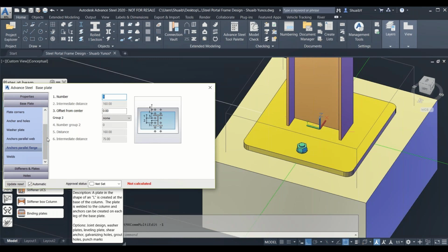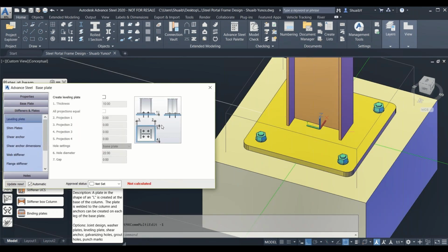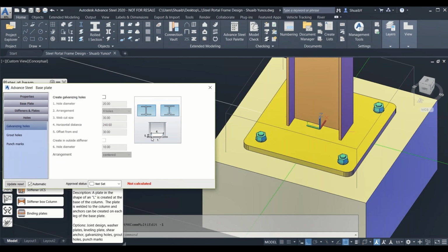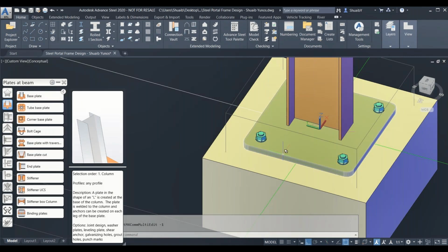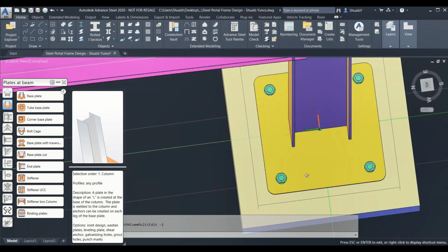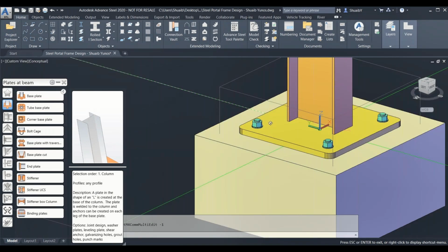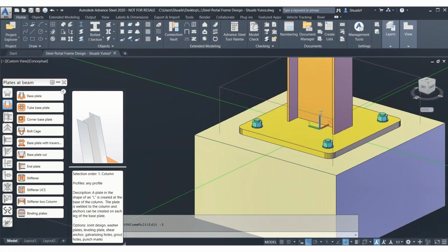Again, you'll know already in terms of your design what distances you're using, right? And now I'm going to offset it again. And now we've got 4 bolts. Okay, so don't forget the flange option. If you see it offsetting in a straight line, please use the flange option. And as you can see, it looks nice. It's what I want. And that is literally the base plate done with the concrete footing.